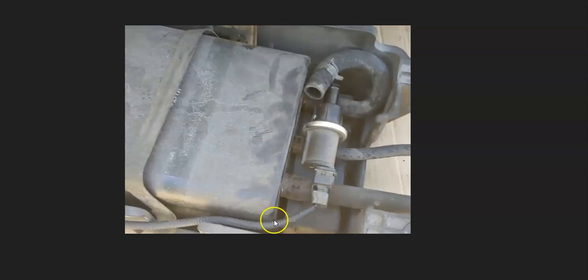And be aware this is usually on a fuse. It's usually inside the engine compartment. There's a fuse inside of there. So be sure to check for any blown fuses, especially if you're not getting any power to the solenoid. So be sure to keep that in mind. But first thing to do, check out this wiring real good, and be sure there's no opens or shorts.